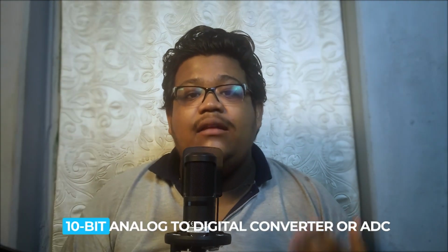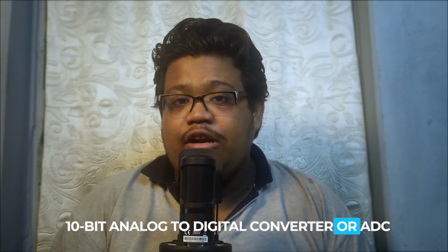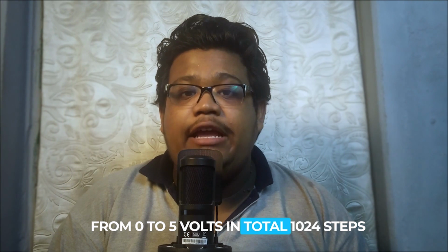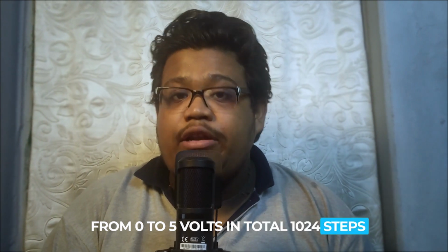So now let's discuss analog input. For taking analog input, we need an analog to digital converter, and our Arduino has a 10-bit analog to digital converter, or ADC. So we can capture any type of analog signal from 0 to 5 volts in a total of 1024 steps, because 2 to the power 10 equals 1024.